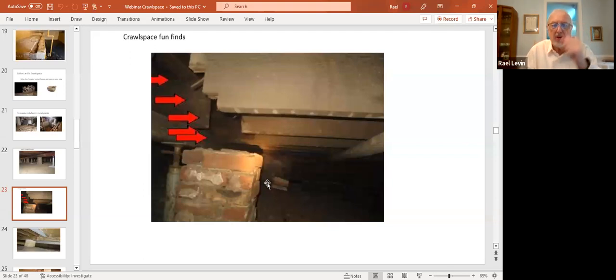But here's a situation where perhaps some permitting wasn't done. And you can see there was a beam here originally supported on this brick pier back here. There's also a plank running on this side, which should have had some supports. You can see the support on this side. So there was work that was undone here, no beam installed. So this one was probably rotted or malfunctioning in some way, sagging perhaps. And they took the old one out, but never put the new one back in there.